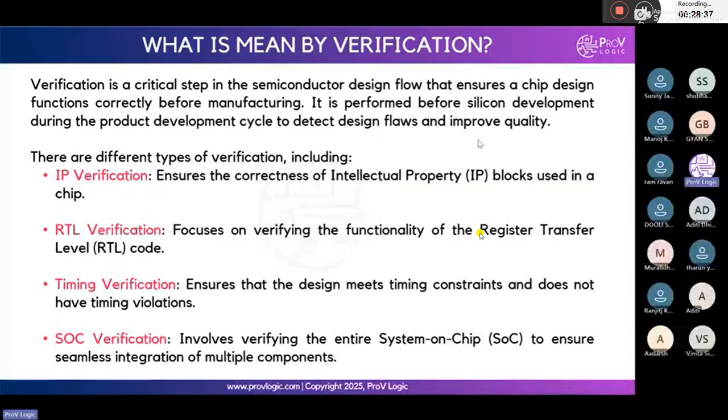But before that, we will have the exact specification and the piece of code we write before, right? Based on that design we also do the verification, because the exact hardware will not be ready. Everything will be there in our server. We do the verification, we check all the constraints and get 100% coverage, and then we make the exact hardware. First we will have just one piece of hardware, and with that we do the verification in post-silicon.